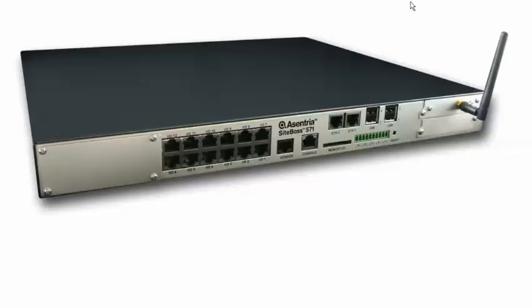The front side is very similar to the 550 we just went over, but it does add some specific newer features needed for this specialized purpose. 12 built-in serial ports allow you to manage radios and power supplies via their console interfaces. A dedicated console port is also available for management of the 571 itself. Like the 550 hardware, 2 Ethernet ports are available. A sensor port exists for connection of external Asentria sensor peripherals, and there is an MMC card slot for upgrades and mass storage.